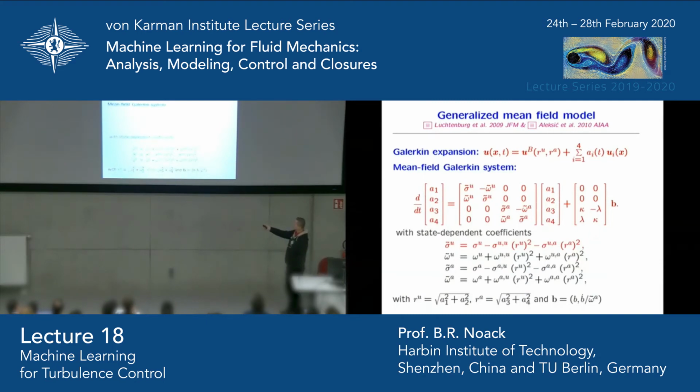Without forcing, this growth rate is positive, so vortex shedding will always want to occur. The shear layer vortices are always negative, so without forcing you would not see them. So you have a damped oscillator here, which you need to excite, and you have an unstable oscillator here, which you cannot directly affect, but somehow they seem to be communicating. How are they communicating? If you look at the growth rates here, you find that the growth rate of the unstable fluctuation has a positive value here.